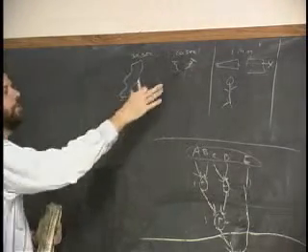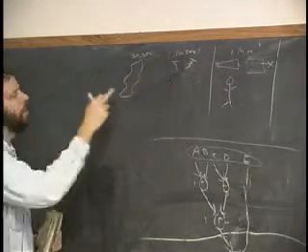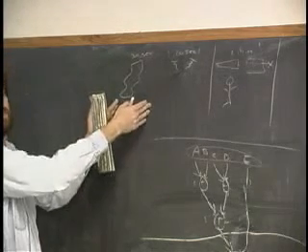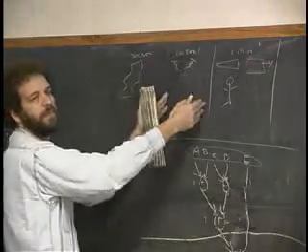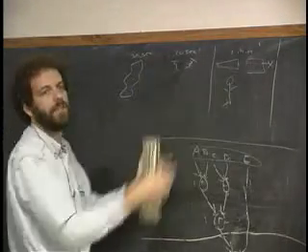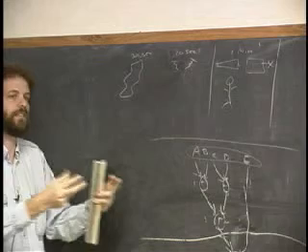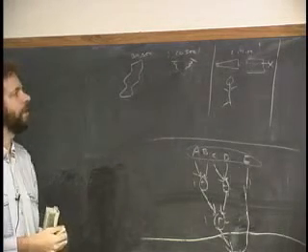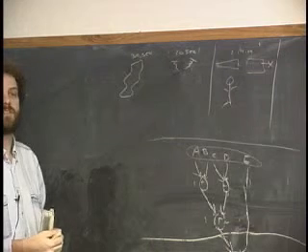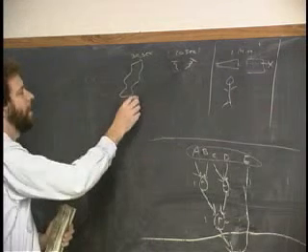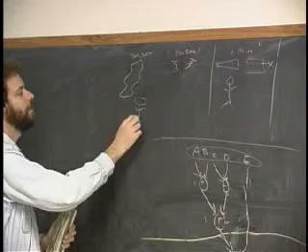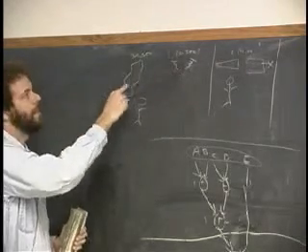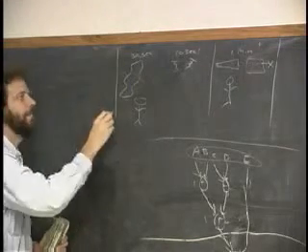How many people should I use to do these 2 jobs? Should I give one person this job and another person this job? In other words, should there be a work cell here that then gets handed off to this one, that then gets handed off to this one? And remember, all the work cells have to get clocked at the same time. Bing, chunk, the whole line does a transfer. That would be a waste of manpower, right? We just have one guy that does both in series without pipelining, puts the weather stripping in, and then puts the bolts in, and we make that be the work cell.